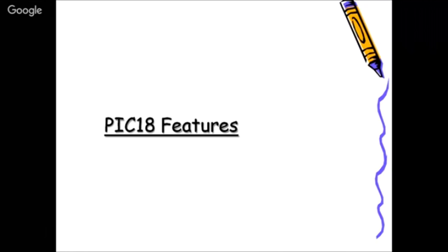Now we'll see a little bit about the specific features. PIC 18 features. Today our interest is only to touch upon some important basics and some understanding about the PIC family. Architecture wise, as I was telling you, it differs from your 8051. In contrast to Intel's basic 8051, which most of us are familiar with, it has a RISC, a Harvard and a pipelining architecture, which makes it very powerful as far as performance goes. As a result, there are so many features also available.